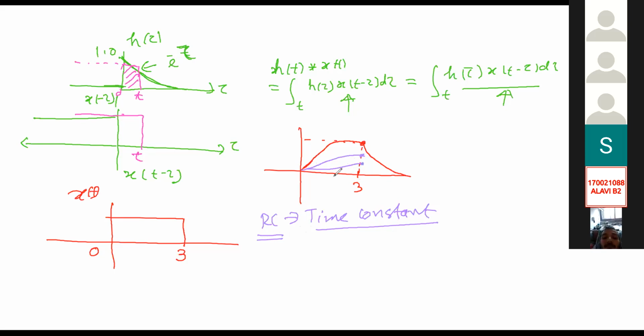For this reason, each oscilloscope has a certain upper range of frequencies. Beyond this, you cannot use that oscilloscope. We have 2 types of oscilloscope: one is analog, another is digital. In the digital case, a data rate is mentioned, the maximum data rate that your digital oscilloscope can handle. Similarly, in the analog oscilloscope, you will have the frequency limit in terms of megahertz. Up to that hertz, you can use your oscilloscope. Beyond that, you cannot measure it. So this is your case.